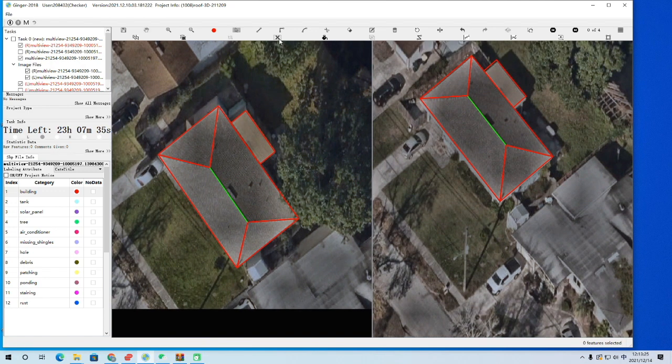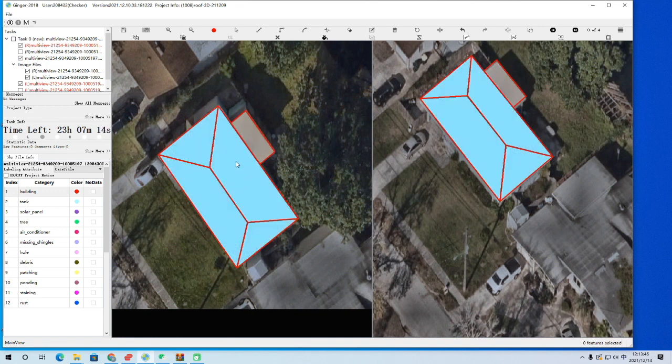We can remove the assist line, and to check if we missed any roof part, we can press the button on the left of the 1 on your keyboard. It will show all the roof parts that have a slope, that have height information, in blue. In this case, you can see these 4 parts have been covered, and this is just a flat roof.